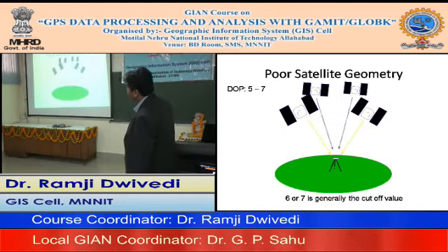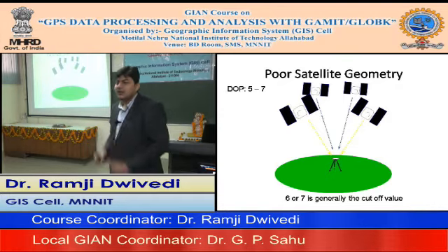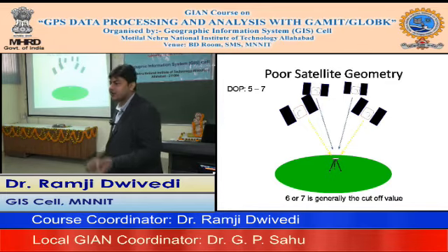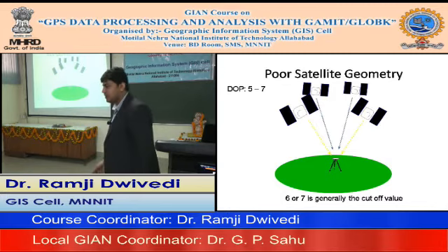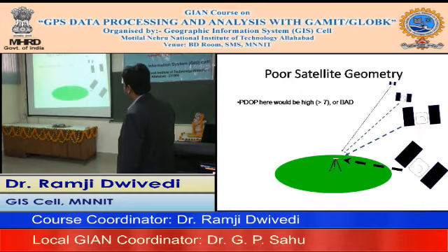That's why on the first day I said you cannot take the next epoch data kind of understanding. With few epochs, say you have only 2 satellites, you cannot take just 3 epochs of data, because eventually that will lead to poor geometry. So this is also one of the ways you could see it.